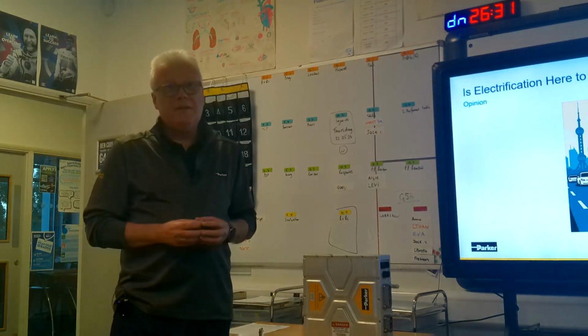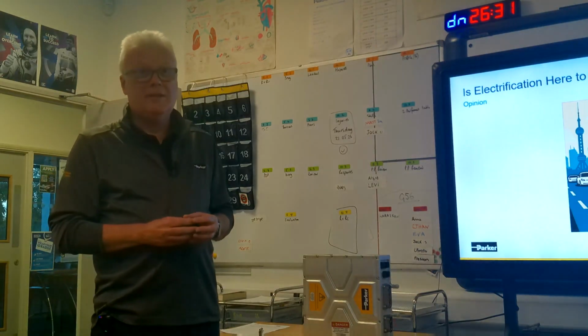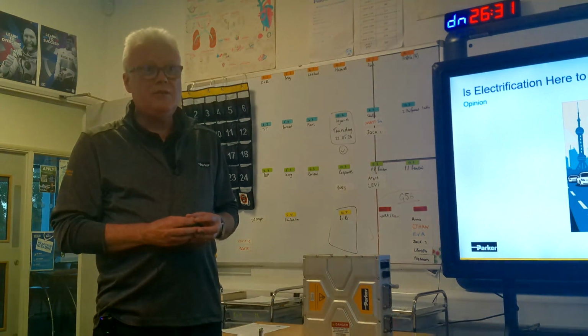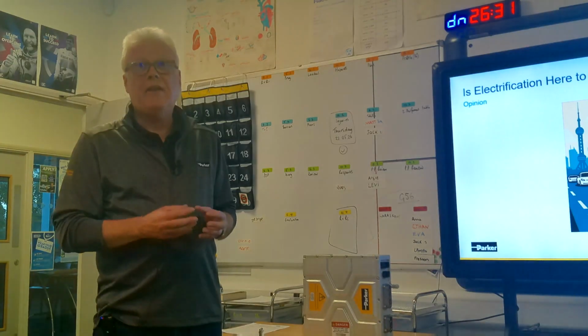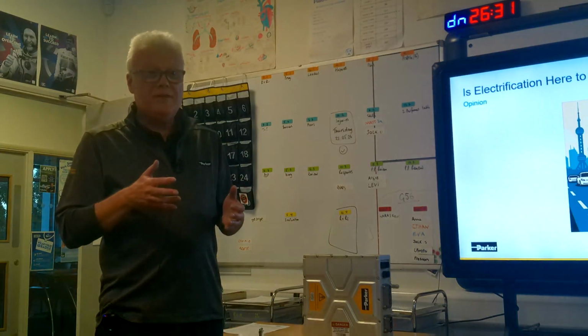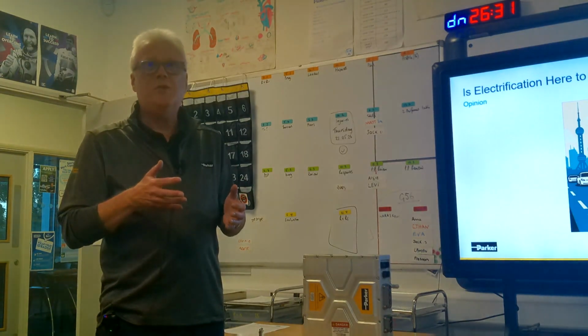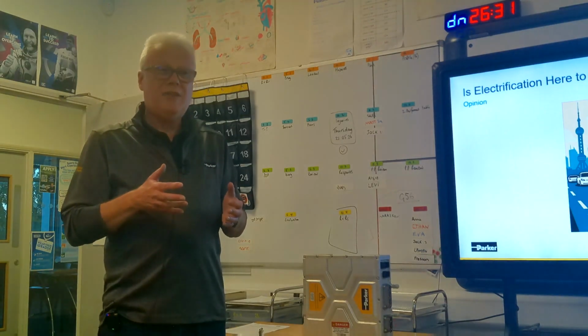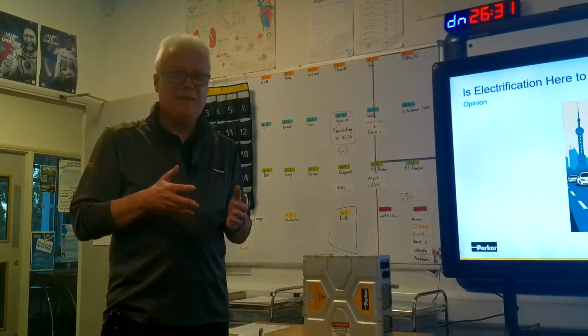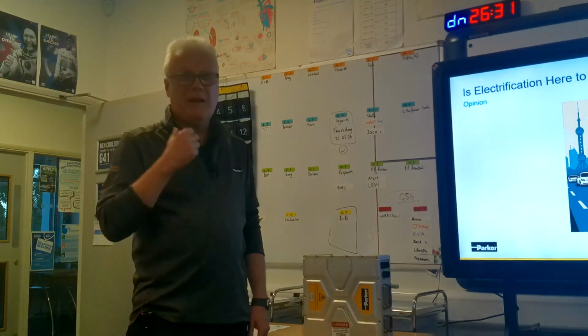So the motors are inboard, but are they solid on the shaft or is there some sort of gearbox between? Typically you can see a single speed gearbox attached. It goes through a differential, yes. There are some vehicles now coming out on the market that might have, say, 2 speeds, okay? And generally speaking, they don't have clutches. And they don't have reverse gears either, because you can just tell the electric motor to go backwards. It's a simpler proposition.